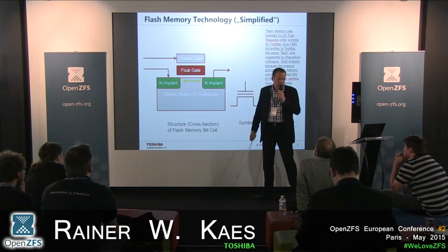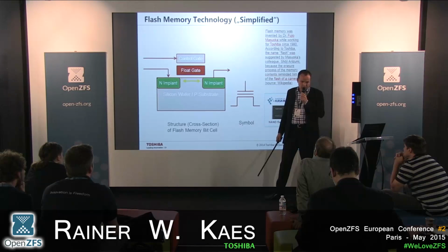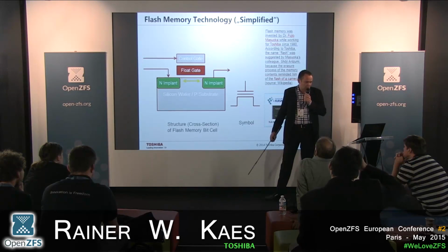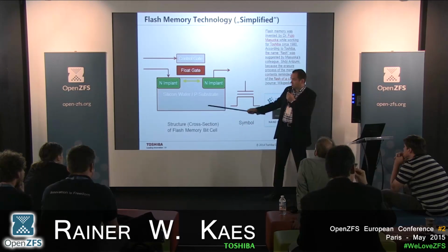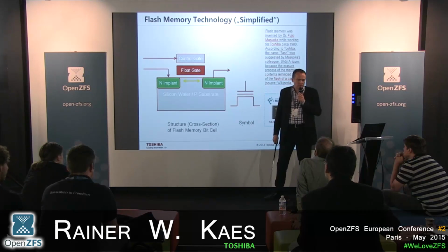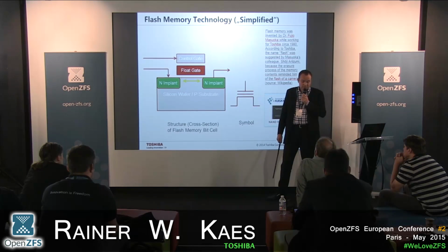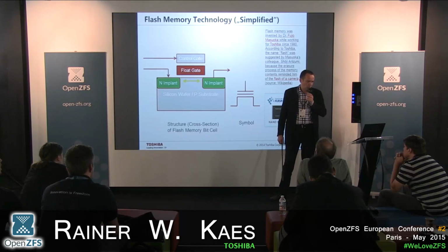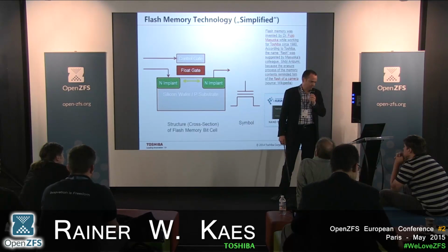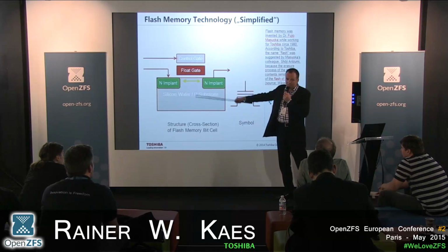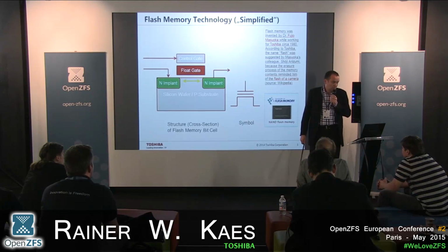The isolation layers are less than a nanometer nowadays, and the electrical field is measured in volt per meter. So 10 volt over a few nanometers is a very high electrical field, comparable to the flash of a thunderstorm. The electrical field on this small area is like the electrical field in the flash of a thunderstorm. This is, by the way, why it's called NAND flash.